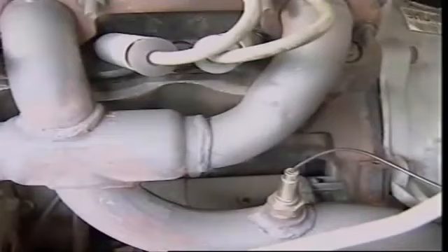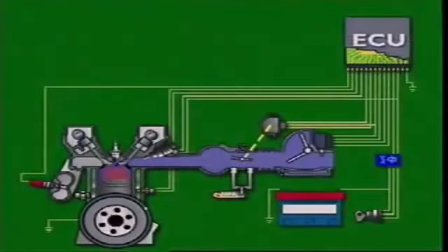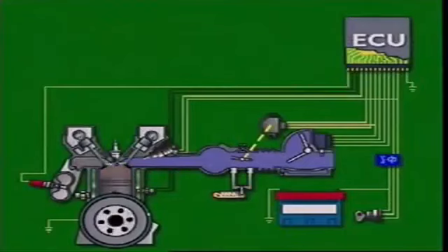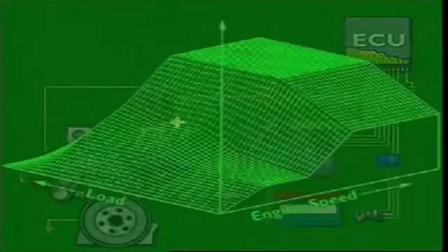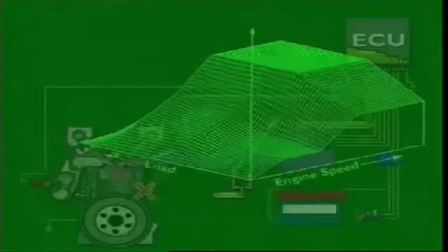One lamp blink, followed by a pause, then 3 blinks in rapid succession, indicates code 13, which may mean, for that application, that the oxygen sensor voltage is not changing, leaving the engine in open-loop operation. When the control unit does not receive a signal from a component, it uses a substitute value from its memory bank. The engine may still operate near its normal level, and the driver may not realize a problem has occurred.